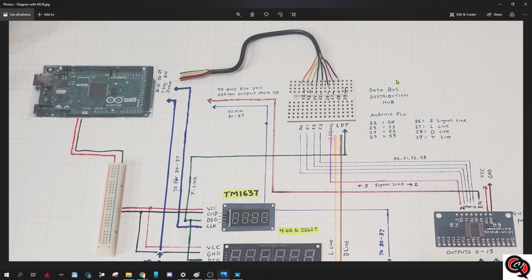So you know, Vlad and Roman from SimVim Cockpit, they don't really recommend that you do things like this with prototype boards, and they recommend that if it's going to be something permanent, you should solder it together, because obviously it's more secure connections. With these, you always have the possibility that something is not making good contact, or that if you move something around, they might just come out of their little holes, and then you're going to be trying to find out what the problem is.